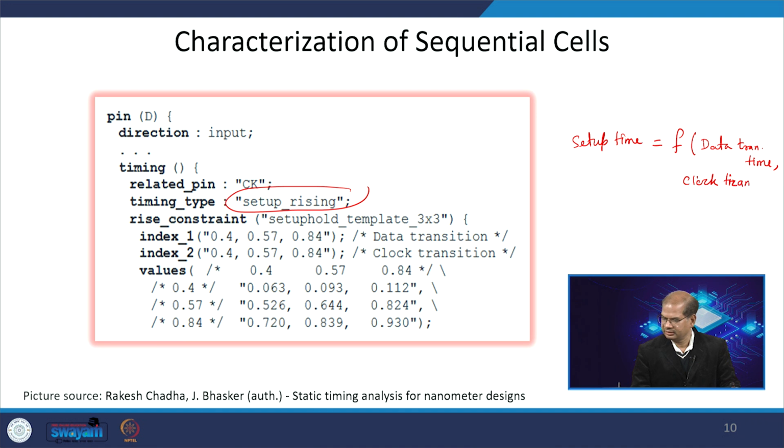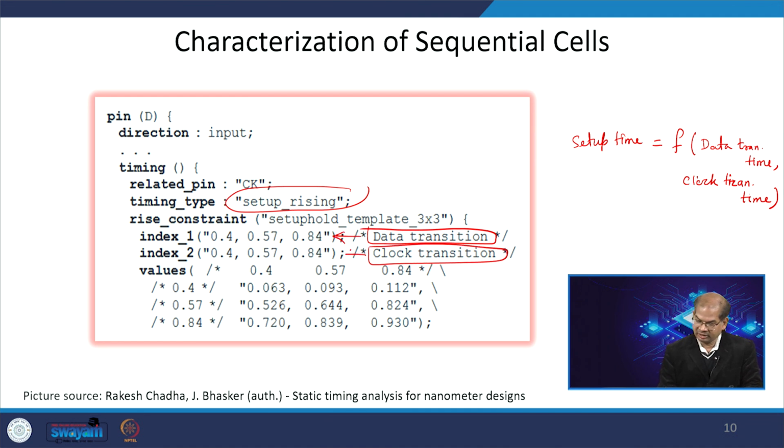It will not depend upon the load. Why will it not depend upon the load? Because the first latch, the master latch, will see the same load all the time. So, it will only depend upon the data transition time and the clock transition time. The first one is your data transition time, then this is your clock transition time.